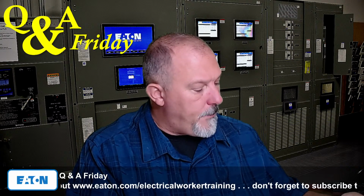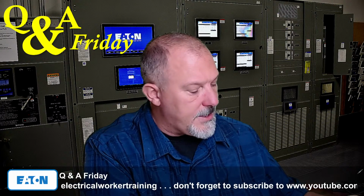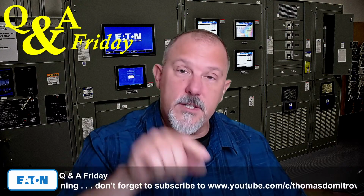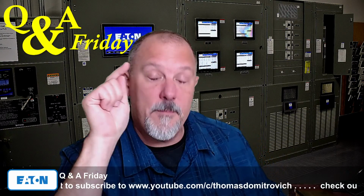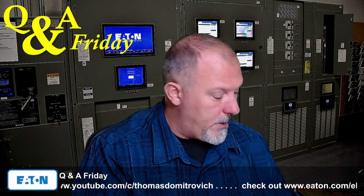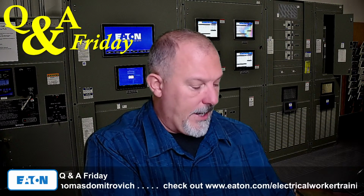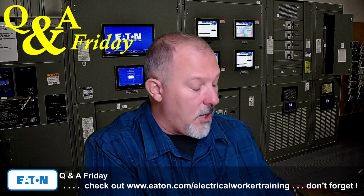The standard ampere rating for fuses and inverse time circuit breakers shall be considered as shown in 240.6(A). And then you have the adjustable trip, because of the long time pickup. You mentioned B and C. I just read A, but B and C is when you have an adjustable trip: the rating of adjustable trip circuit breakers having external means for adjusting the current setting. And it does say long time pickup setting.